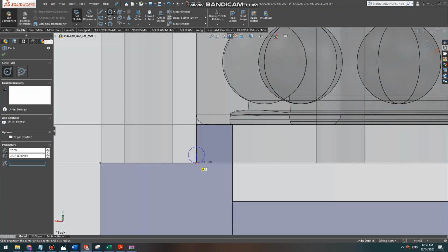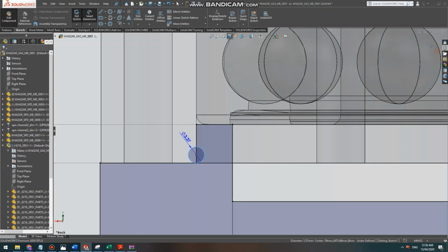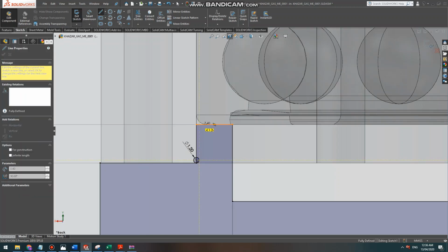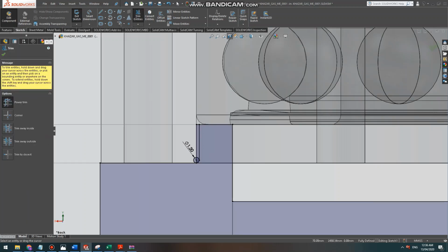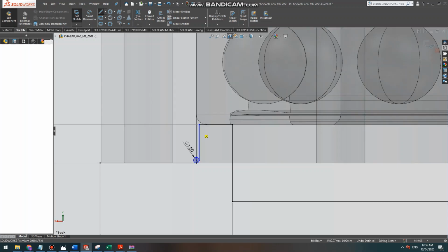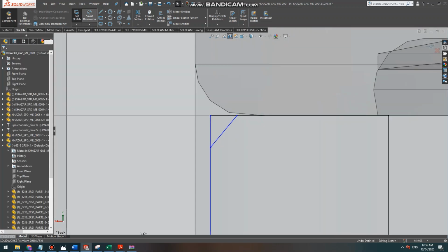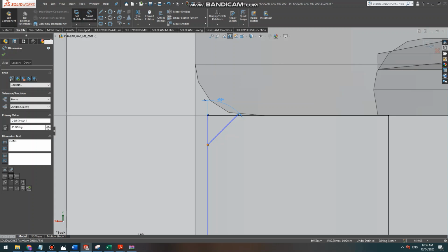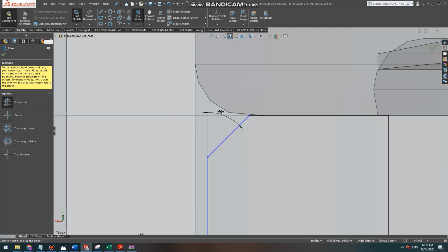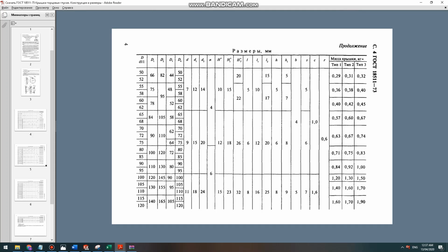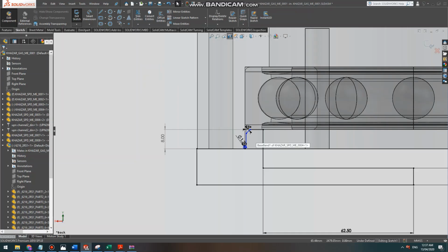So we make a radius here. It will be 1.2 diameter, and from that we are drawing this line here, and we do the next step, and we make a fillet 1.6, so it's 95 degrees, and it's 1.6 millimeters on each side. And yes, we delete this. That's it, I guess. Let's look. Yeah, perfectly. C by 45, C is 1.6. I think that's perfect.